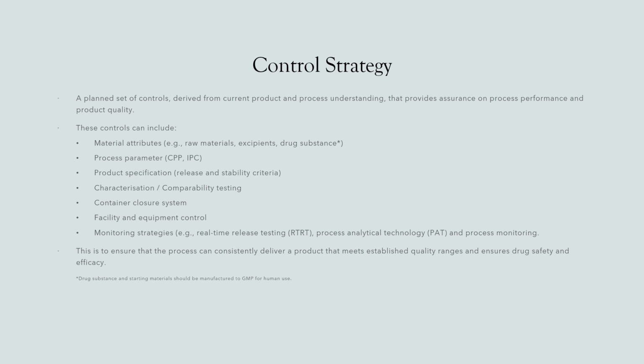And the critical process parameters are what you need to be monitoring, obviously, because they're going to affect your critical quality attributes. There's a direct or maybe even indirect relationship to your critical quality attributes. So the critical process parameters are what you need to monitor and control, because variability in those parameters may impact the quality of your final drug product.